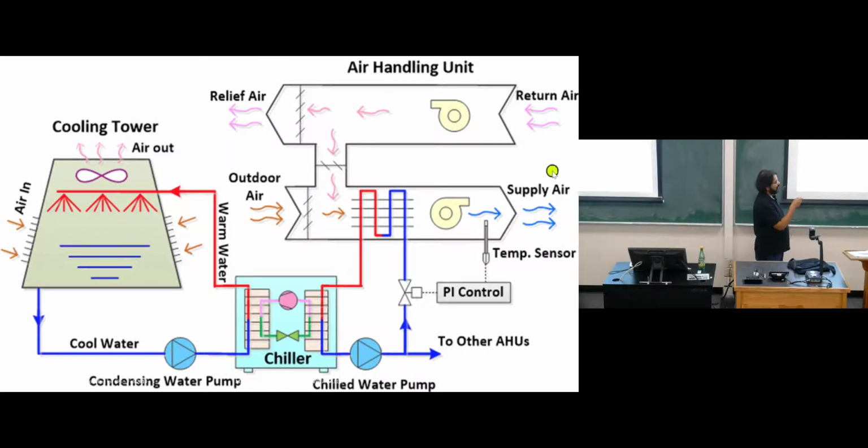There's some heat transfer which is not shown on the slide, but the air which comes back is warmer because of this thermal exchange inside the room. And that's why we have to continuously condition this. As a result, this chilled water which has been circulated is also gaining some temperature. Now this high temperature return water goes into the chiller, and it has to be brought back to its original 42 degrees Fahrenheit set point.